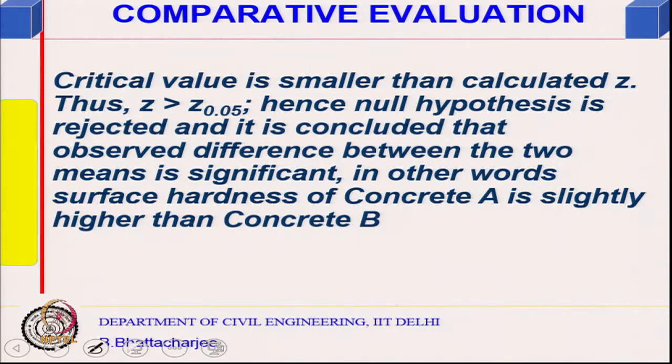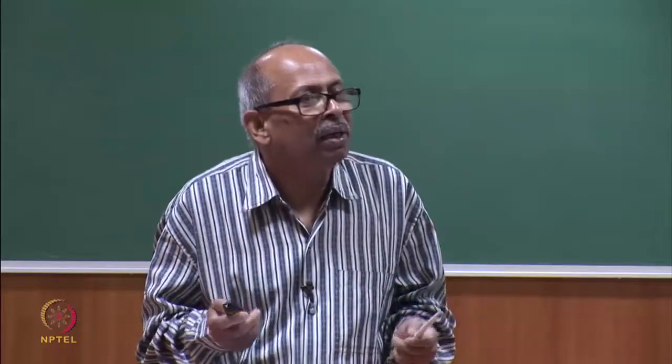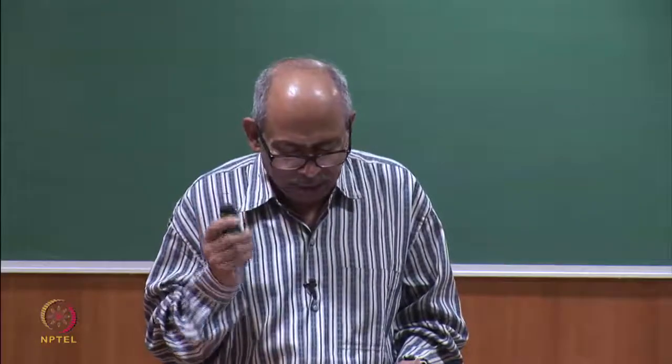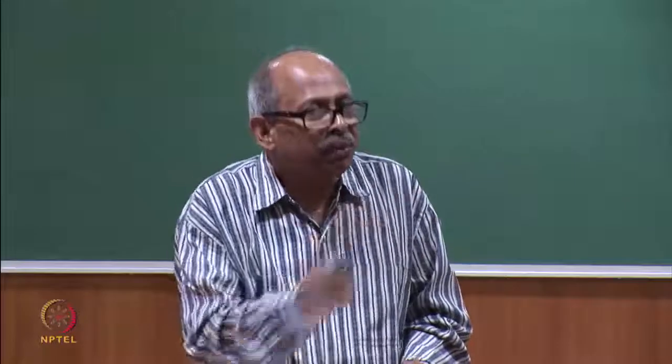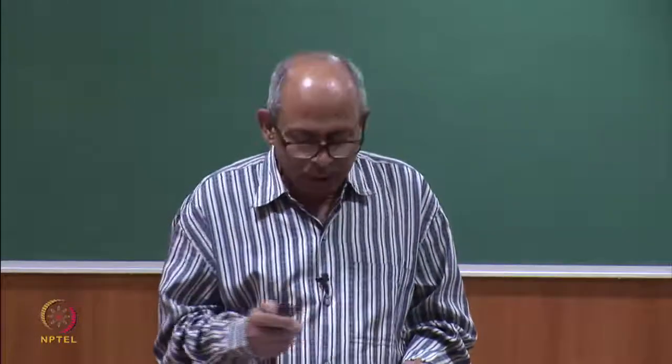And we could conclude; I am not going into the statistics unless you are interested, you can look into the detail available here. We could establish that concrete A is as good as concrete B by doing simple statistical testing for each type of test: first for the rebound number test, then for the ultrasonic test, and then for the capo test.